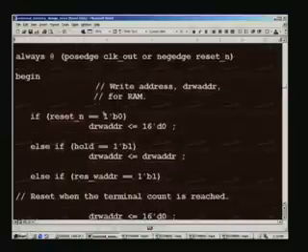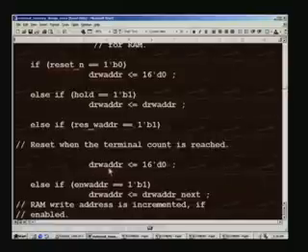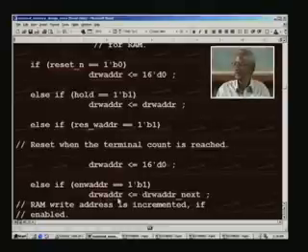And in the next block we process the actual, that is only an assign statement earlier. So, what we do is we really process only here based upon the reset write address, and we have seen there, and we reset the address because it has touched 65535. So, we need to reset that one, and it will be reset at this point of time, and so long as the enable is on, which we have seen the condition earlier, and the write address is incremented, this also we have seen in an assign statement earlier.